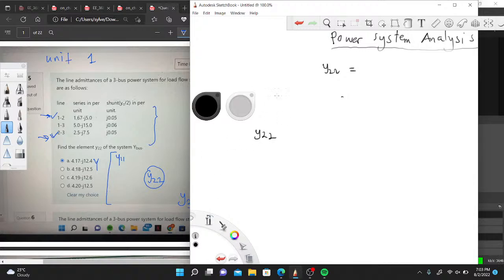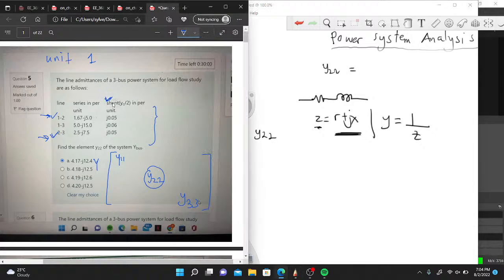Transmission lines are modeled in 2 ways. They can be modeled as short lines. As a short line, a transmission line is made up of a resistor in series with an inductor. So for many of the calculations where we see Z equal to R plus jX, we are considering the short line model. We just need the R and the jX as our impedance, and then our Y will be 1 over impedance.